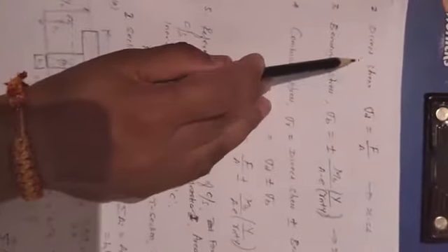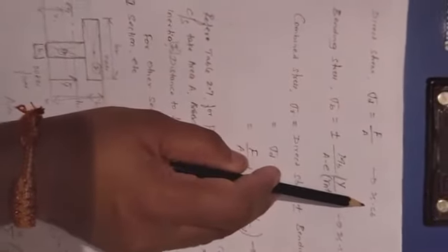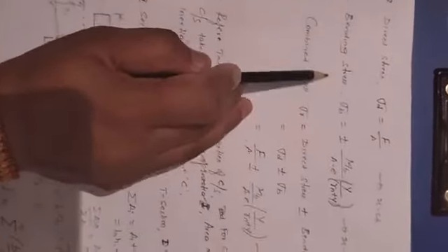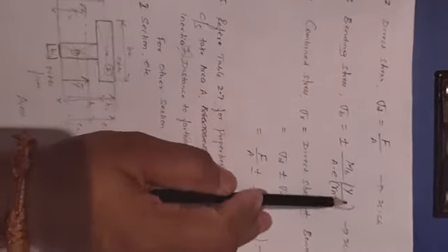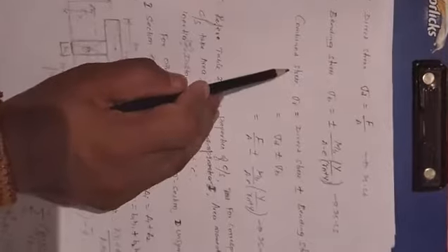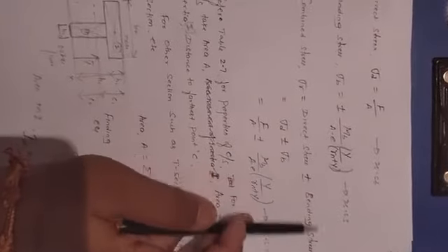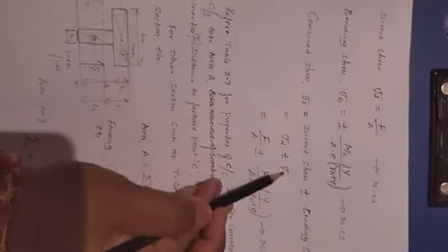And other formulas you can see that. Then what are the stresses active? Direct stress, as you know, is force by area, equation number 25.56. Bending stress, already we know that, plus or minus M_b by A into y divided by R_n plus y, equation number 25.53. As you know, the combined stresses are the direct stress and bending stress, plus or minus, or you can use only plus, direct stress and bending stresses.